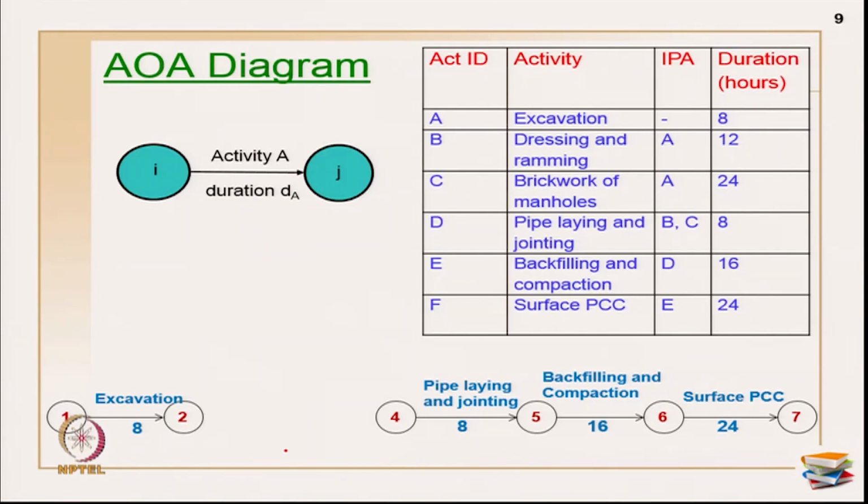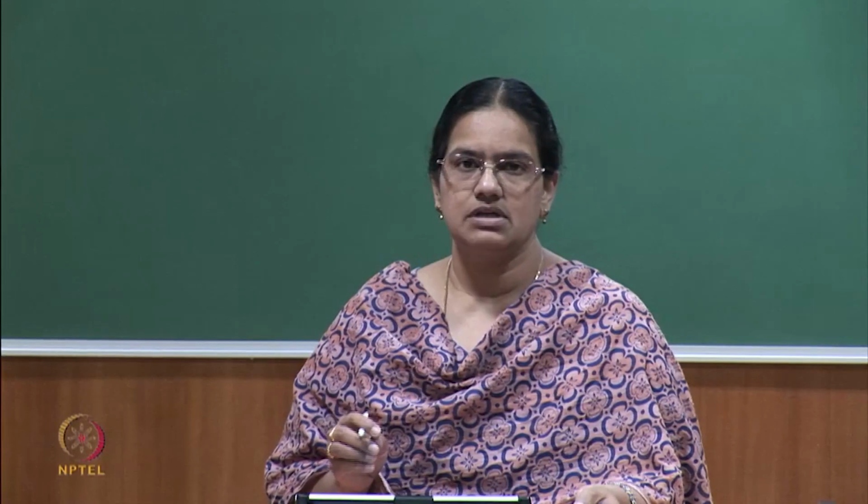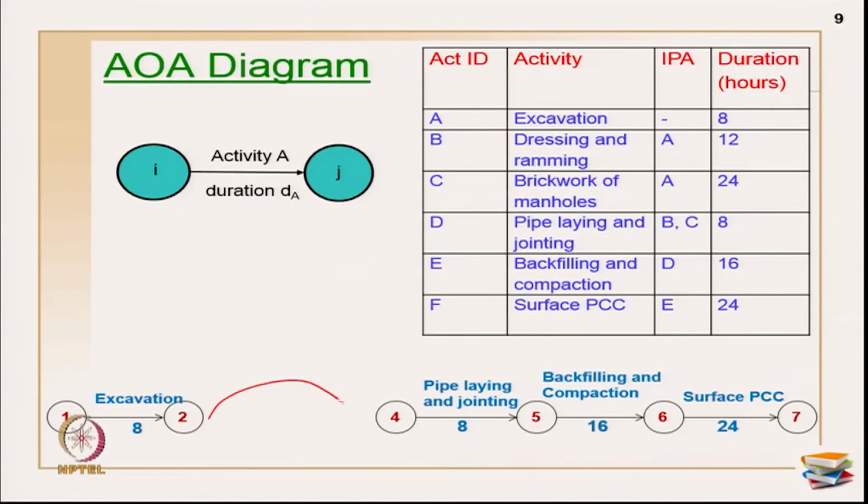Okay. And the duration and the activities are represented along the arrow marks. Generally, activity is represented above the arrow mark as shown here, and duration is generally written below the arrow mark as seen here, and numbering is also done. Now, in this particular case, I am going to introduce a dummy, because if I connect the 2 activities like this, I am going to share the same IJ for both the activities. So, I wanted to avoid that.